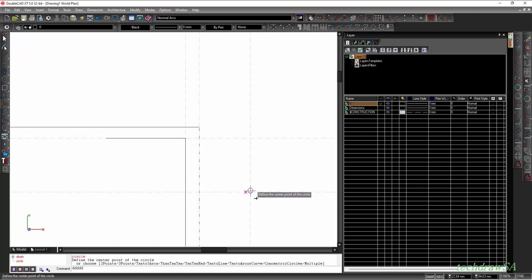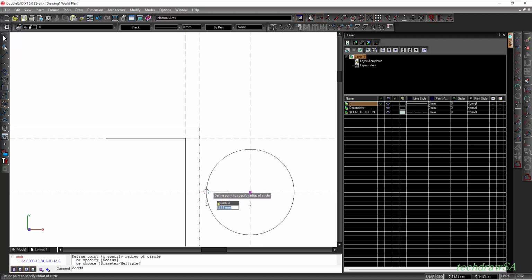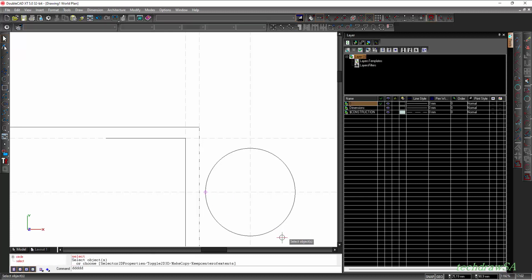So, and then I have my center lines as a center point, and then I can just add the JoJo tank's distance there, and obviously we'll have a little gap between the JoJo tank and the wall itself, and then I'll just click off on that. So there I have a very specific placement of my JoJo tank. Now you can label it and you can add your water, plumbing and everything that you need. Yeah, and that is how you would specifically snap a certain feature next to a wall.